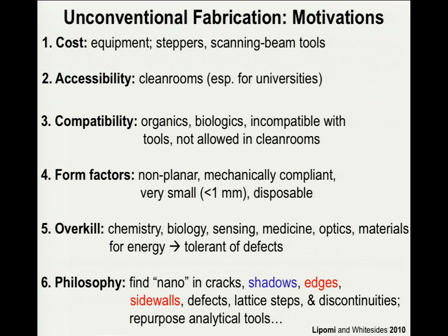One of the approaches is to repurpose an analytical tool for the purposes of fabrication. If you look at the history of nanofabrication, most of the tools were actually developed for imaging, not for production. The optics used in photolithography were derived from microscopes. The e-beam writers were derived from electron microscopes. So often we take something that was made for analysis and we repurpose it for manufacturing.